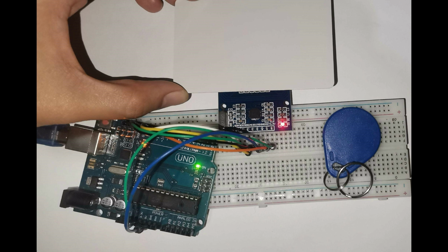Wiring wizardry. Connecting to the invisible. Follow the wiring diagram. Ensure you have the correct one to connect the RFID reader's serial output to the Arduino's serial port. Disconnect the reader during sketch upload to avoid interference.